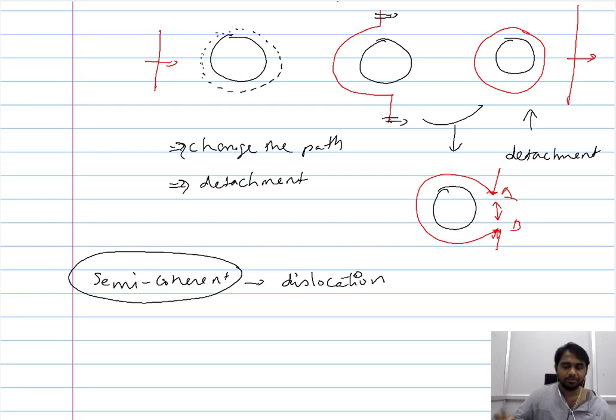So these are sometimes referred to as the misfit dislocations. These misfit dislocations are present in order to bring about continuity in the atoms between the two phases. You have atoms in two phases, and there are continuities in some regions, and there are these dislocations. These dislocations are present in order to bring about this continuity, and they are associated with the interface.